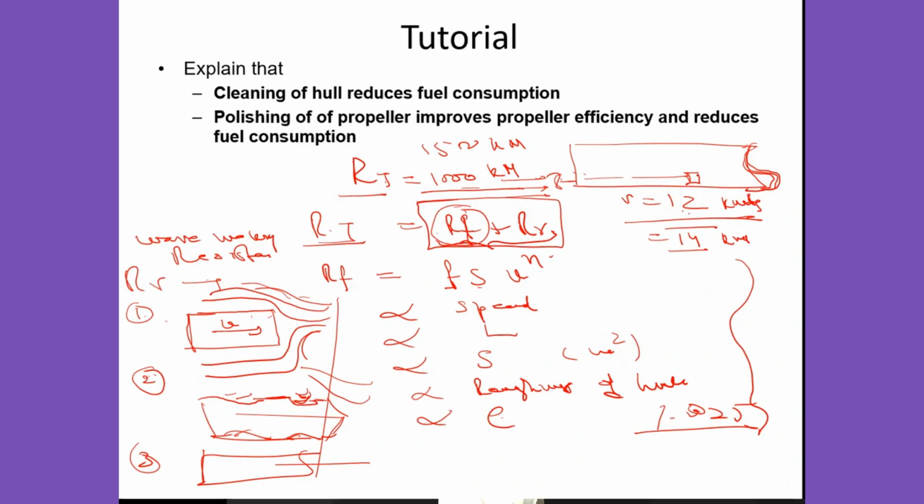As the vessel moves at slow speed, as you said, the example of a bulk carrier moving at say 12 knots, this part is a very small component of the total resistance. Out of that 1000 kilonewton, this may be only 5% or 10%. That means frictional resistance is the major part of the total resistance, and therefore power required is primarily to take care of the frictional resistance.